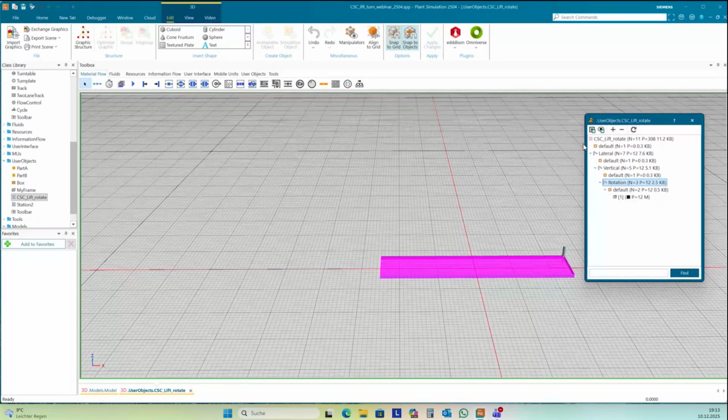If you have a robot in Plant Simulation and the robot is able to move like it should move, then you will also find such a structure with 4 or 6 animatable objects, one inside of the other. If you have only a flat structure, then it doesn't work.